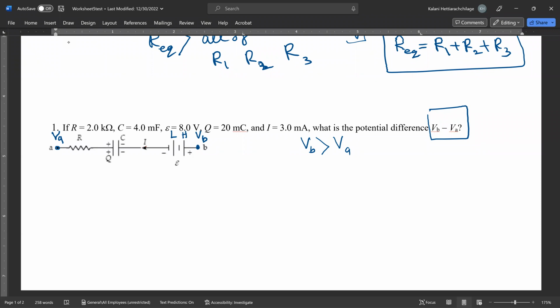In addition to that, as soon as you see the resistor, you know that the current is going from right to left. Because of that, the potential at this point is lower than the potential at this point, right? Because the current flows from high potential to low potential through the resistor. So now only the capacitor is left. The capacitor has two plates that are already designated as positive and negative. That means with the positive and negative labeling, this terminal has high voltage and this terminal has low voltage, because negative is the neutral or negative terminal, right?